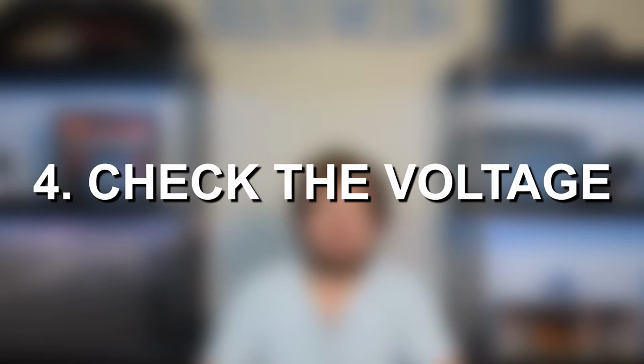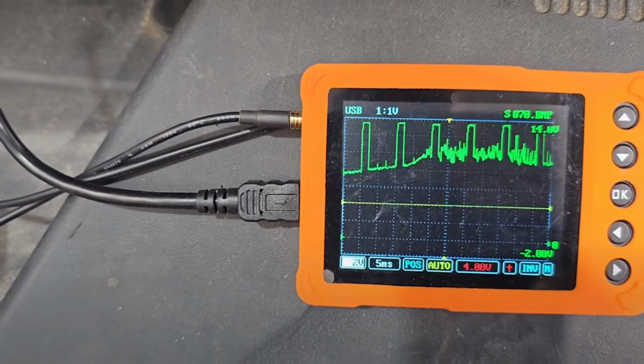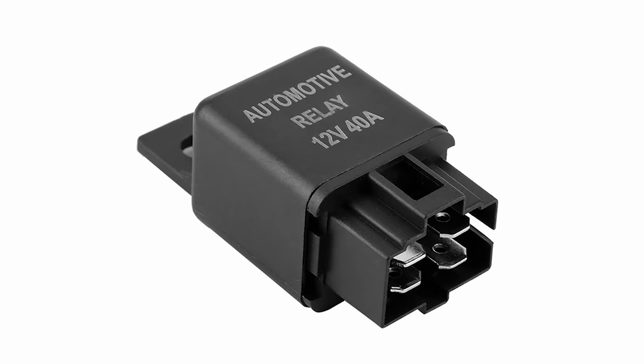Once you've checked that and confirmed that there aren't any basic issues, and you know that you're trying to diagnose just fault code P0480, then the next step is going to be testing the voltage to the cooling fan and all of the sensors. Ensure that they are receiving that signal, and once you confirm everything is receiving the signal, you can then pinpoint, depending on where there might be signal issues or voltage issues, whether it's an issue with the cooling fan itself or potentially the cooling fan relay, which again, a lot of the times is going to be the most common problem that causes fault code P0480.